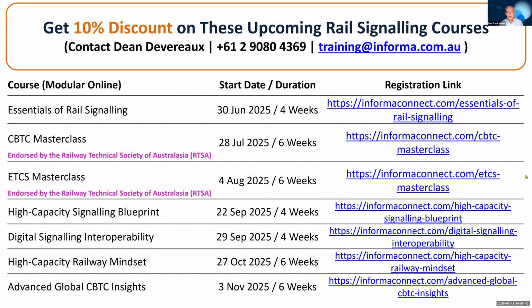I don't really find this, to be honest. The suburban trains are in many cases quite modern, and you can definitely apply the principles of modern train control to increase capacity. Maybe you don't get the same effects as you would for metro, where you have specialized trains with extremely good acceleration and braking performance. But that doesn't mean you can't do anything at all. You can still apply these technologies to suburban operations, and we are showing this as we speak in all the major Australian cities. Perth contracted CBTC mid last year, and they're now starting to roll it out, and they will be able to increase their potential capacity by more than 150%. So to me, that indicates that suburban railways are very suitable for doing these things and can provide a massive uplift of capacity everywhere.